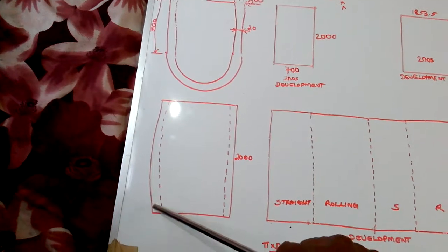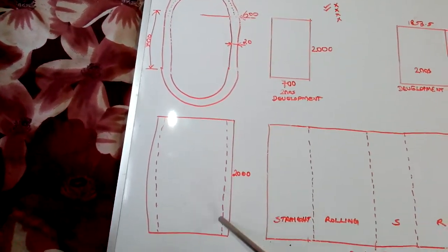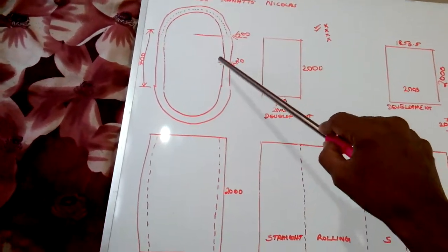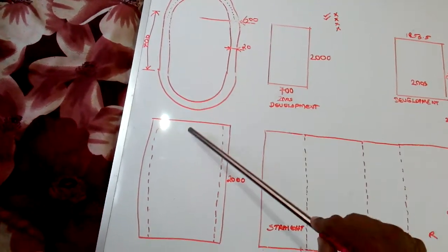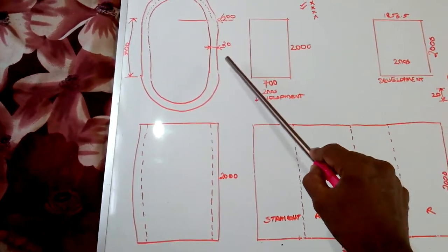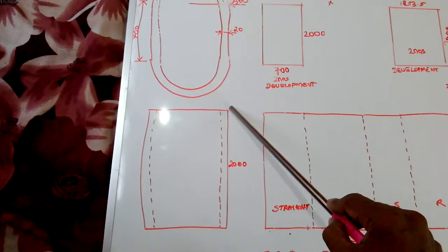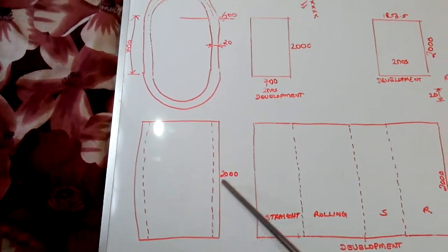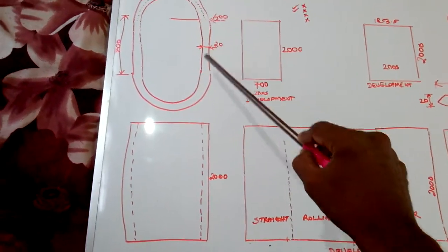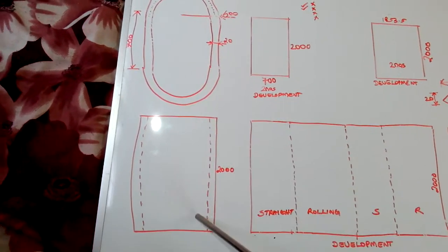It is a thick line. Inside we can see one dotted line. Why has it been drawn as a dotted line? Because when we look at this job from here, we can see its outer surface only. The outer surface we see as a line, so it has been indicated as a line. But the inside wall is there, though we cannot see it, so we have to indicate it as a dotted line.